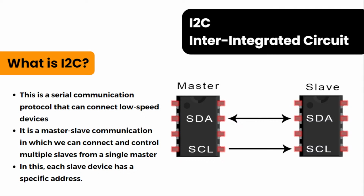Like SPI, I2C is synchronous, so the output of bits is synchronized to the sampling of bits by a clock signal which is shared between the master and the slave. The master always controls the clock signal.